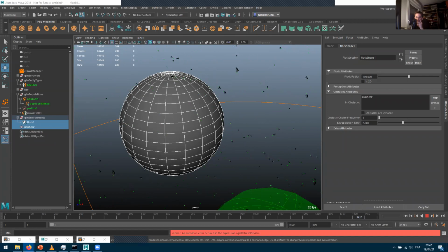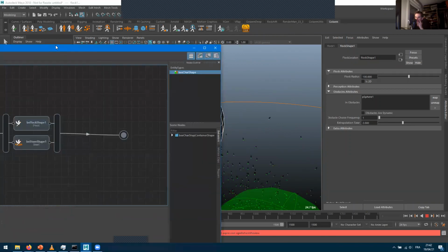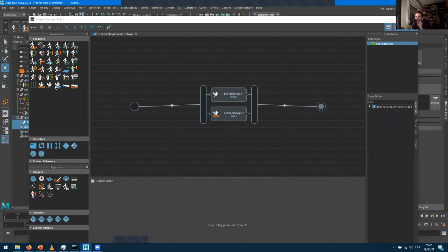What if you want all bees to land on that sphere? Well, I'll let you experiment today or tomorrow or when you have time. You may have noticed that there's one extra behavior we haven't spoken about, which, if I stop my sim, is called perch on. Detect perching objects on current trajectory and perch if detected. Maybe you should take a look at that one and see if you can make it work for your own requirements. Let us know.